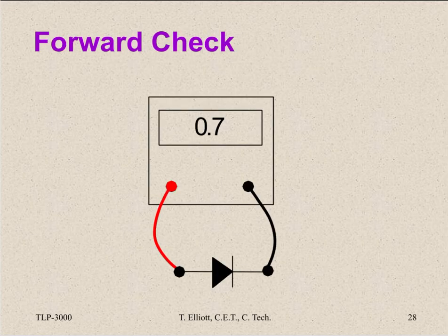Diode testing. You can use your diode check on your multimeter. When I first made this presentation 25 years ago, the testers weren't commonly available, but you can buy component testers. Amazon has them. $50. It'll measure everything. It's really quite amazing. But use the diode check on your multimeter. It'll be 0.7 volts turn on voltage. It might be less, but ideally it's 0.7.